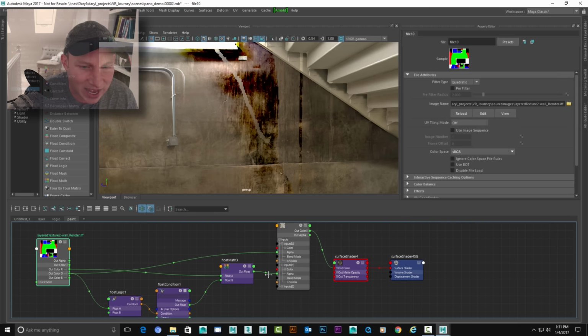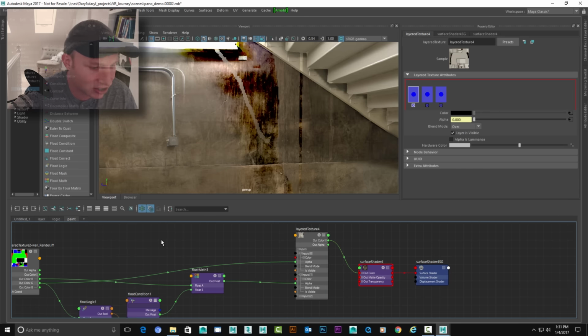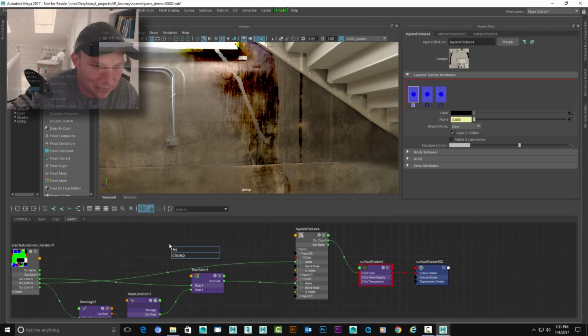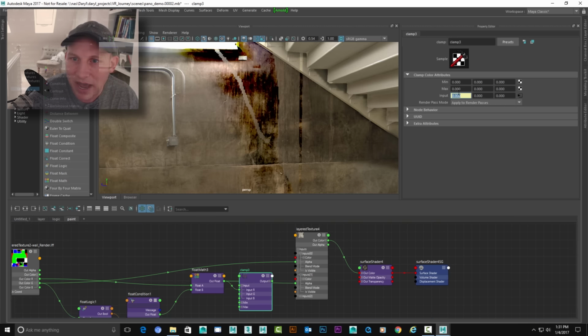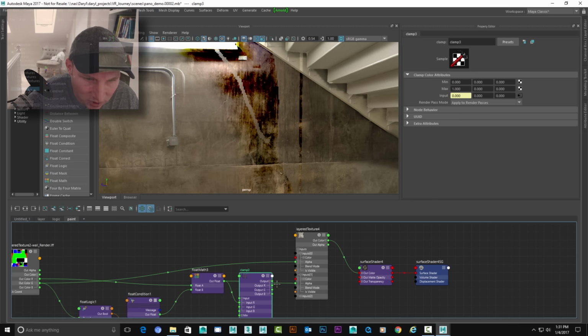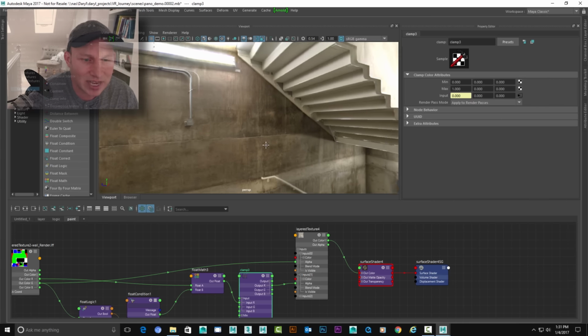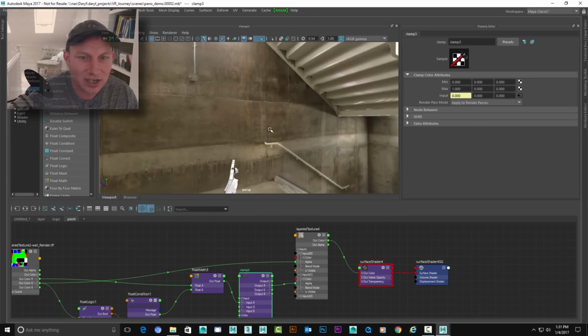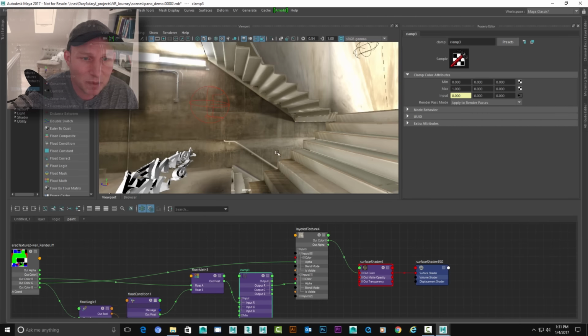So what we're going to do is add in a very simple clamp node to clean that up. If you're in here and you click the tab key and start typing clamp, click down with the arrow key and bring that guy in right there. We're going to go to the inputs for this guy, go to the red channel, and say min-max 0, 1. So now we can take the output of this guy, output red, into the alpha for that guy. And now we basically have a file that does exactly what we want, that transitions between all three of those. So that is basically it.